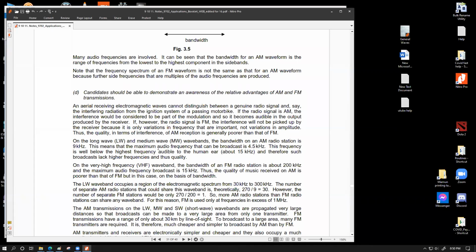Within an AM channel of long wave through medium wave, we can transfer up to a maximum of 4.5 kilohertz of original sound. Any sound that has its frequency above 4.5 kilohertz, we cannot input within this AM station, which means the sound that we are capable of transferring will not be as varied as it could be, or would not be as shruti madhur as it could have been, because of the lack of space for frequency variation.